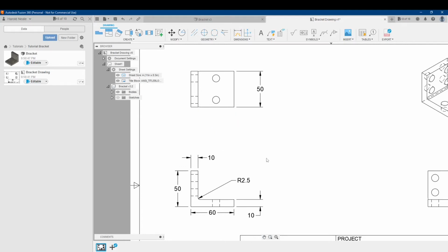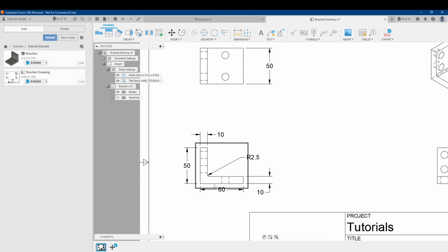So with these dimensions, you might have to do some math too, which I'm hoping that if you're doing CAD stuff, you're already okay with doing math. So, for an example here, this whole length here is 60 millimeters, and this whole length here is 10 millimeters. And you want to know how big this side is here between this corner and the fillet. So you take 60 minus 10, you get 50. You take 50 minus 2.5, and you get 47.5. So let's see. Yeah, you see? So that's another thing with the dimensions. Have enough dimensions that if you can figure out something mathematically, it's okay.